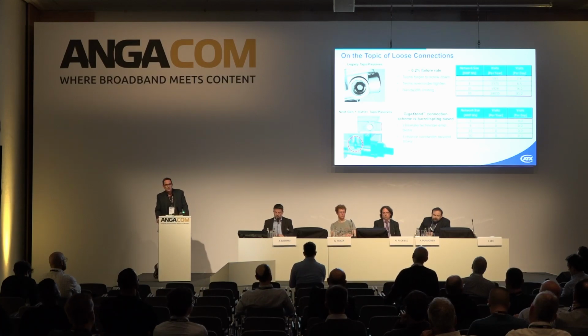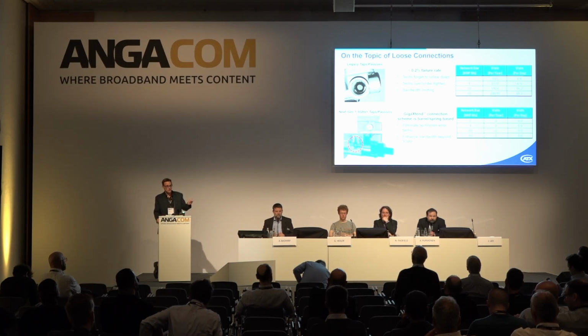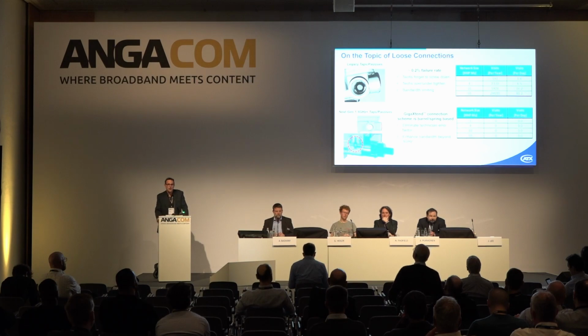Just before we get into some of the details around the costs, this was one of the interesting findings in this study. This is actual data from one of our MSO partners. They had started to collect information on what the sources of maintenance activity were, and they actually found a 0.2% failure rate with respect to loose screws, either the screw down on the hardline stinger would back off itself, or technicians would forget to tighten it down. 0.2% doesn't sound like a lot, but as you can see in the table in the top right, depending on how big your network is, it translates to many truck rolls a day that are potentially avoidable.